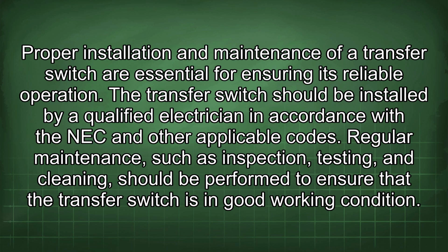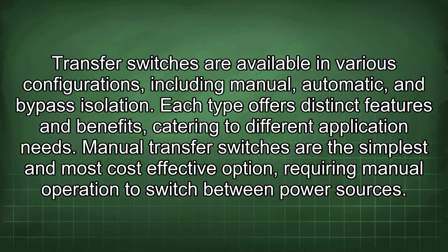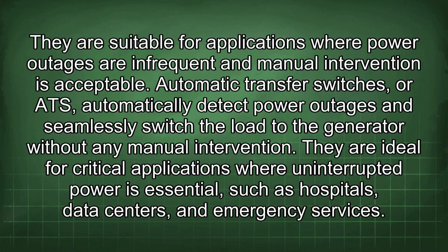Transfer switches are available in various configurations, including manual, automatic, and bypass isolation. Each type offers distinct features and benefits, catering to different application needs. Manual transfer switches are the simplest and most cost-effective option, requiring manual operation to switch between power sources. They are suitable for applications where power outages are infrequent and manual intervention is acceptable.